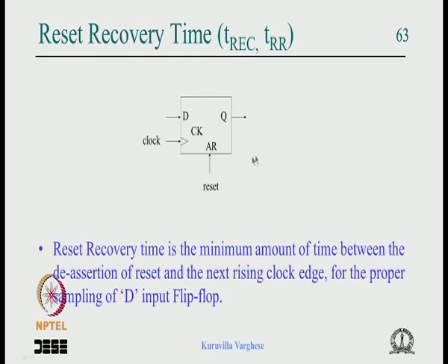So you would see that most vendors or designers would advise you to use synchronous reset because it is safe. But there is a nice feeling about asynchronous reset: the flip flops are reset without a one clock period delay, because in the case of synchronous reset there could be a worst case one clock period delay for it to reset.